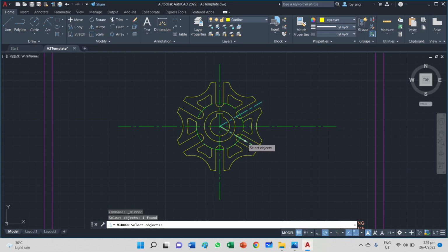I did not choose to rotate the center lines because what will happen is that I will have duplicate center lines, and that won't be good because you have 2 lines on the line, and that's not right. Okay, then you select your mirror plane and you press enter.